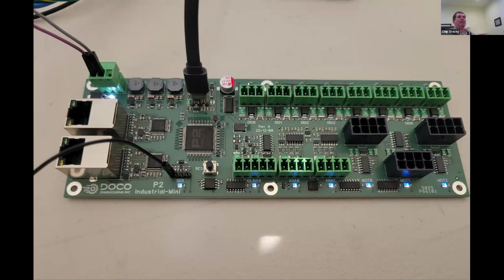it would give me the next LED output state in a flag, like the Z flag, because the carry flag is already being used for shifting bits along that big data chain of the 594s and 165s. So I needed a way just to get the next bit into, say, the Z flag. That's why I chose the Z flag. So every time I call this thing, it gives me the next bit. And there are 3 states, right? There's that initial, what's typically an initial high, but that can become a low if you're doing one of those rest periods or the reset.